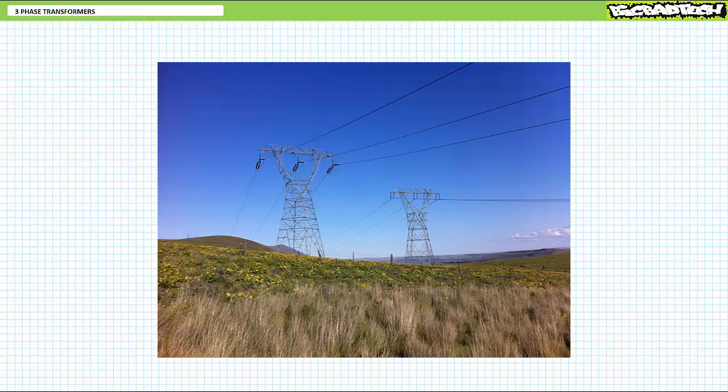Finally, if we were to fully expand our perspective about the purpose of three-phase transformers, it really is all about phase shift. As we'll learn in later lectures on AC transmission, power lines are not the idealized zero-ohm unreactive conduits you may think they are, and at risk of oversimplifying it, it often necessitates a phase shift from one end to another to push power to its intended direction.